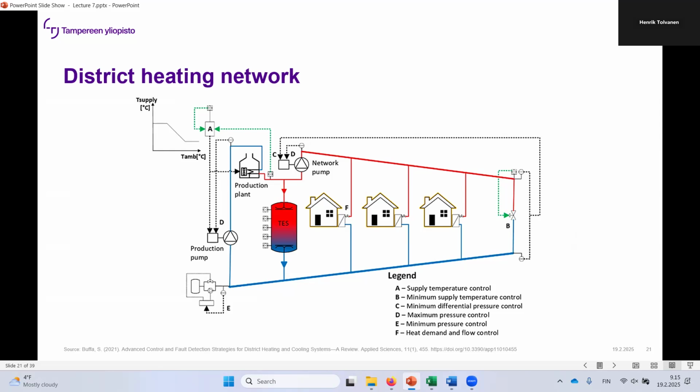And you have to have a certain amount of pressure difference that's managed by these pressure valves. And then you have these pumping stations. So you have to increase the fluid pressure for it to flow. The flow always goes from higher pressure to lower pressure. So we have higher pressure here, and you have to have high enough pressure for the fluid to flow. And what's restricting the flow is the friction. So the more you pump, the more friction, and the more it costs.